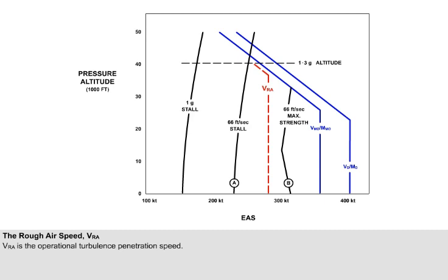Line Bravo is a curious shape, because different parts of the structure become critical at different altitudes. This line is actually the lowest speed boundary of a collection of curves at the higher speed end of the chart.